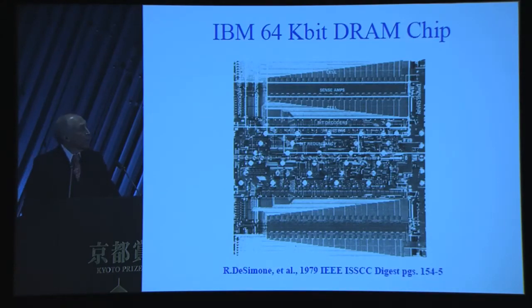The technology developed for this chip was scaled sufficiently to be able to produce a 64 kilobit chip. The sense amplifiers shown on this slide were based on a new self-compensating design technique invented by my associate Dominic Spampanato and myself. I also contributed to a new technique for adding redundant bit lines and word lines, which can be used to replace defective lines to greatly improve manufacturing yield. This technique has been widely used for both DRAM and static RAM for many generations since then.